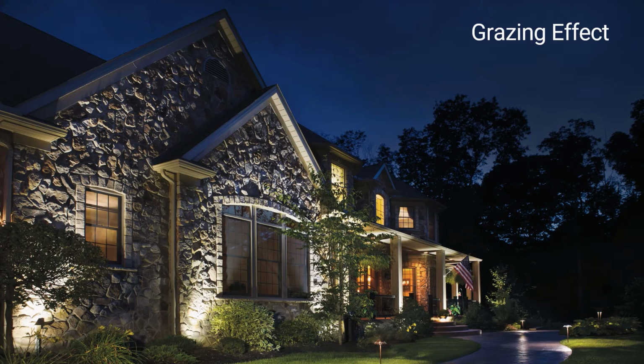When an uplight is placed very close and often at a severe angle to a highly textured surface, it is called grazing. The grazing effect delivers bright dots of light at one side of the texture and exaggerated shadows and dark on the opposite. As you move away from the light source, the light and shadow become more subtle.